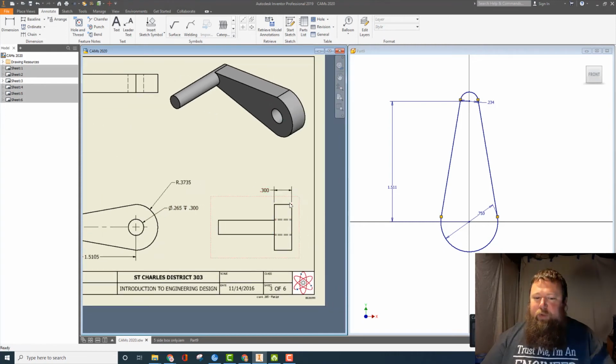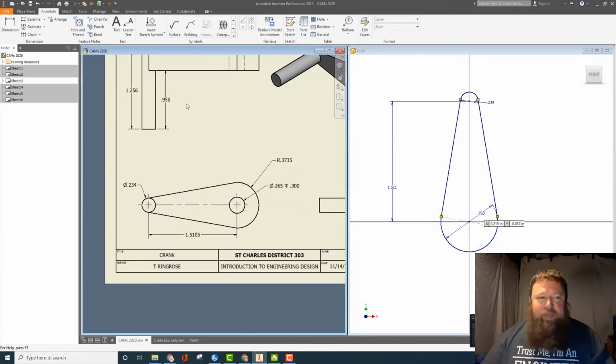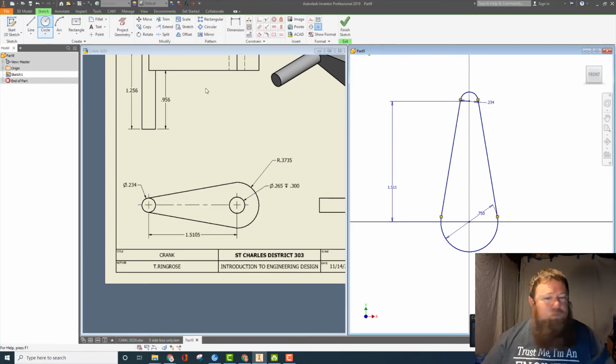If we look over on the right side view, we can see that 0.3 inches is our full thickness. So this is what's known as a through hole. Sometimes you'll see this listed as that dimension and then the letters THRU, as a through hole. In this instance, it's just telling us the depth, which is fine. But I need to add that hole in, and I can see my centers line up, and I want this to be 0.62265. There we go, and I'm ready to extrude.